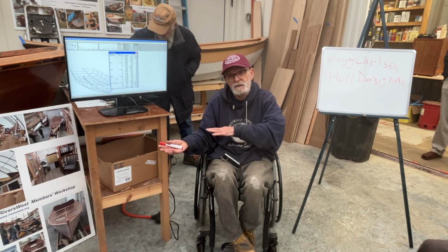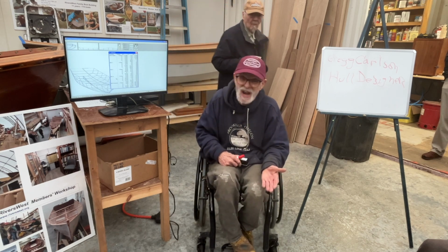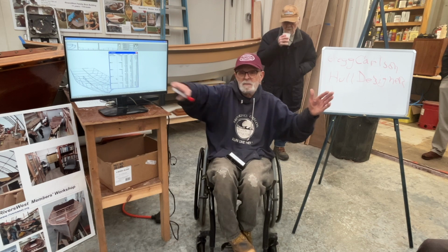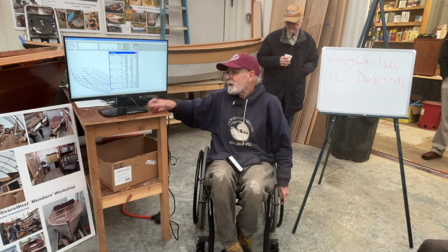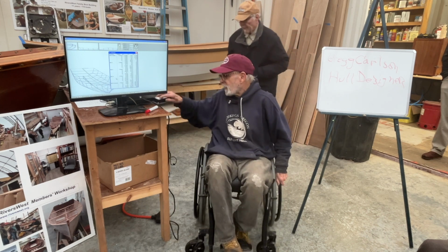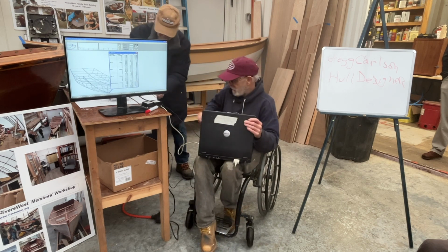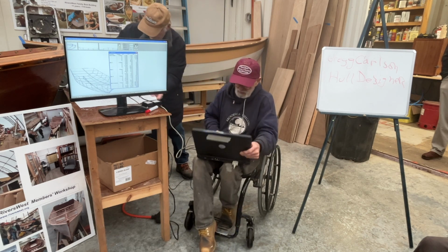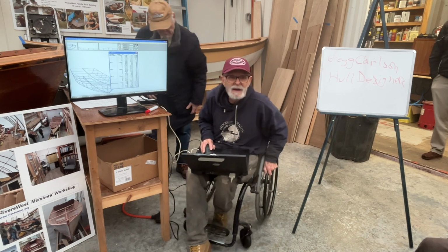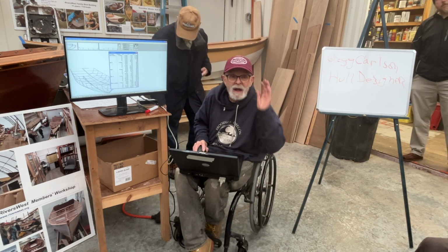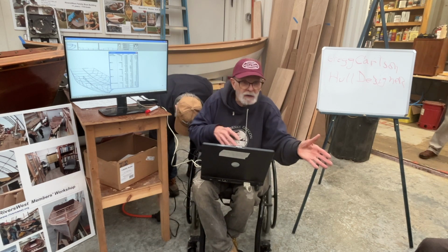Sometimes the mistakes aren't crucial, but sometimes there's as much as 3/8 of an inch, 1/4 of an inch out. For some things it doesn't matter. If it's on the sheer, big deal, you're going to plane it out. But in other things, let me go into the graph program and I'll show you just how bad some of the plans are. One thing I've seen is a lot of the plans don't have enough diagonals. They'll have one diagonal. And I never use diagonals, and I never use buttocks.